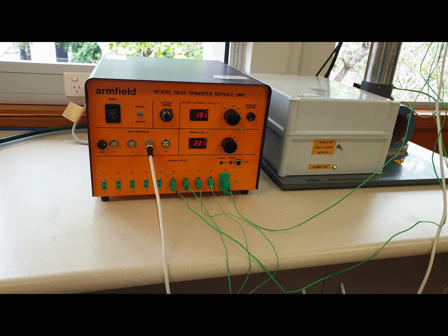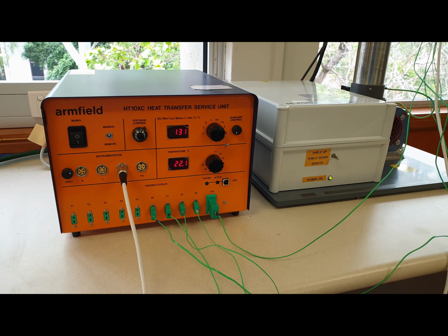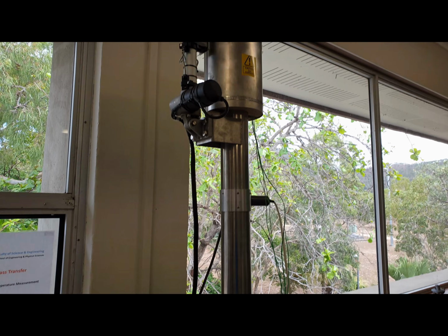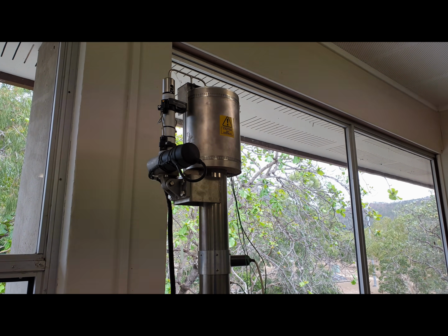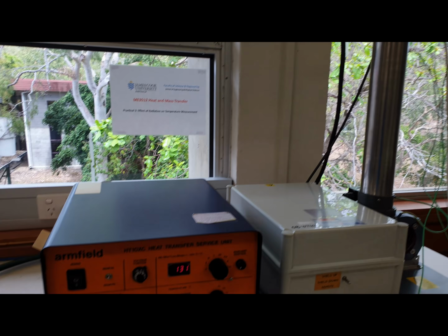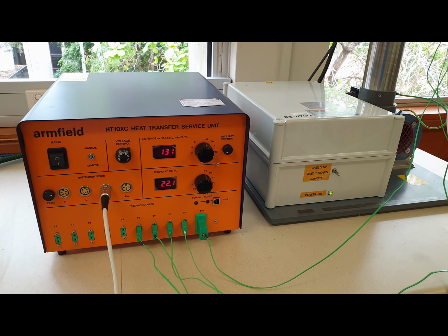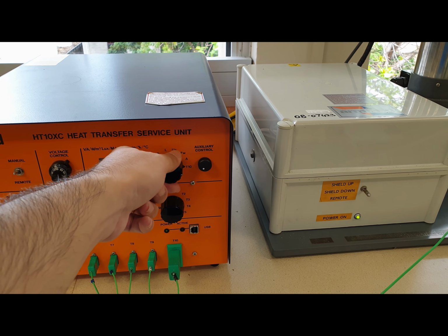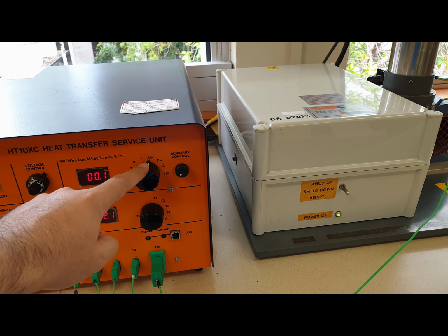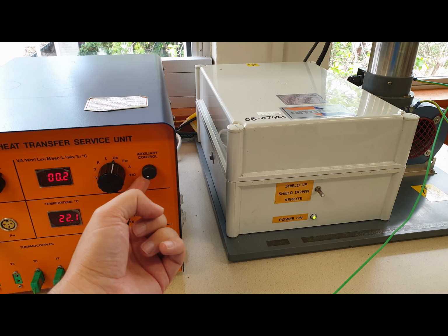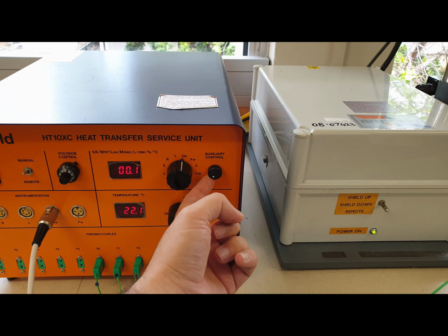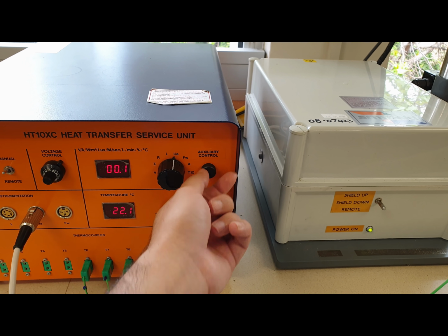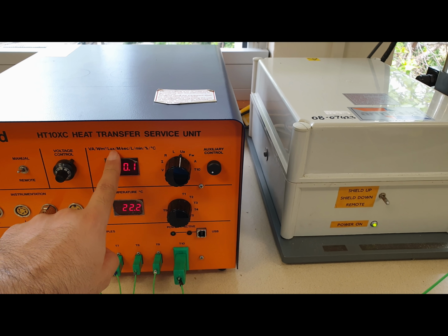Now I'm going to start test 2, which is we are going to have still no radiation, so our shield is going to still be lowered, so no touching the radiation shield, but I'm going to apply some forced convection by increasing the velocity of the fan. So let me rotate this to UA, which is the velocity of the air, and by rotating this auxiliary control, I'm going to read the velocity here. Currently it's almost 0, so let's increase and put it at 4 meters per second. You can see the unit here, 4 meters per second.